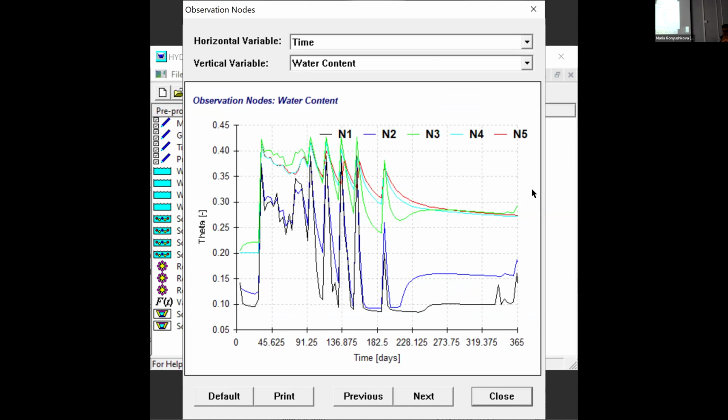This is the result of the first year, the water content. The green one is often saturated, completely saturated. The red one corresponds to the 50 centimeter. The light green one is for 40 centimeter, and that was 30 centimeter. Which means the deeper layer is more or less saturated and has too much water in it. But at the top, we have like 50%. Yeah, it fluctuated during the season.